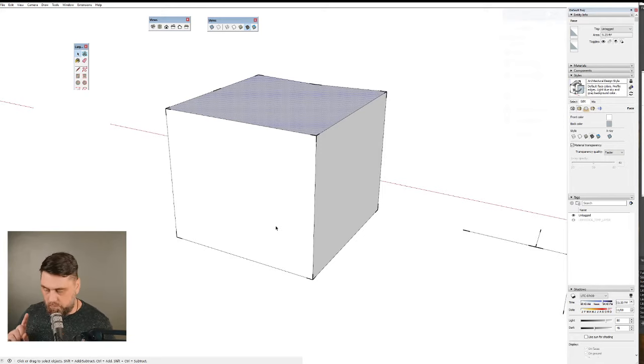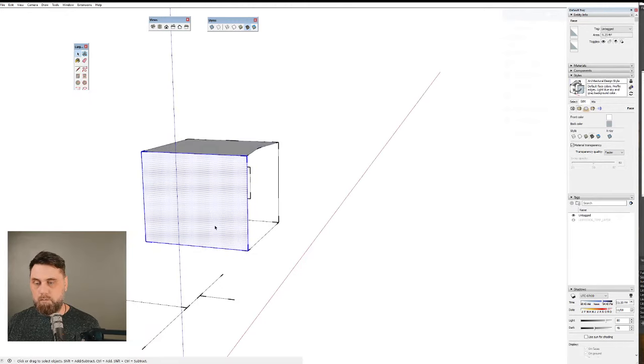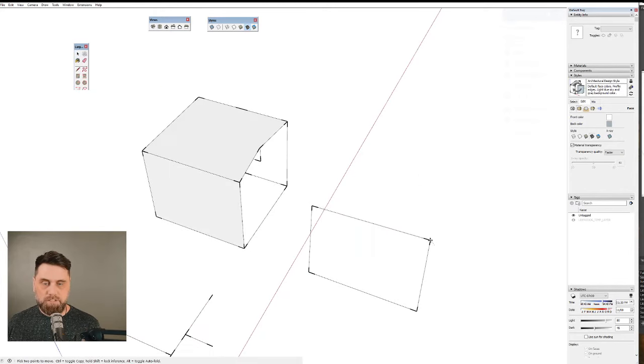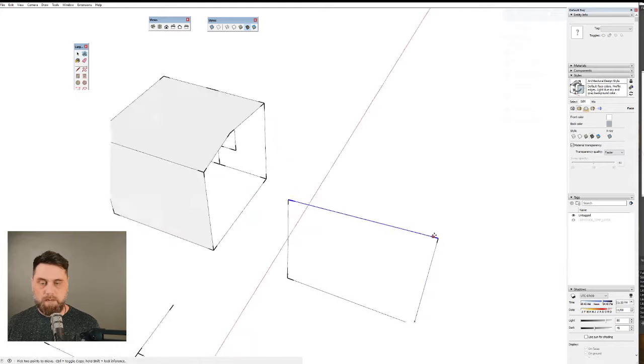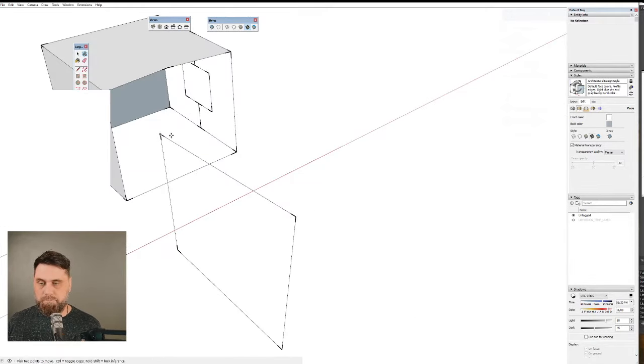And one of the things that's really, really important to understand is the concept of things being plumb, right? Just like you couldn't come and attach sheetrock to a wall that was way out of plumb. Or if you had a corner and we had a wall like this, and let's say one of these corners was pushed back just a little bit out of plumb or out of square, so this wall was not flush with everything else.